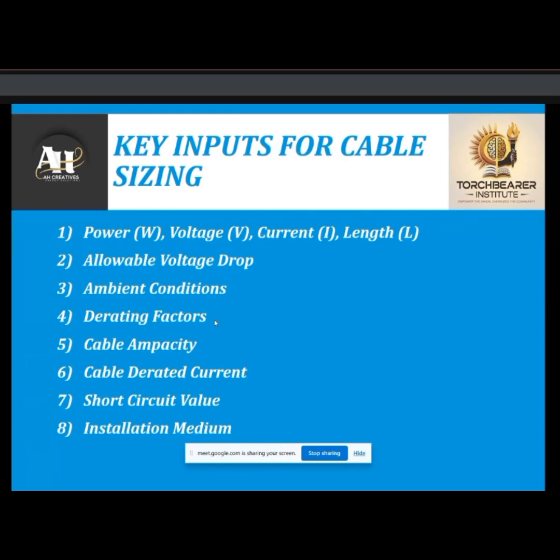And then the installation medium. I have already discussed the installation medium in which the cables are installed: overground in the cable tray and direct to the walls, and underground cables in the duct bank and the direct buried case.